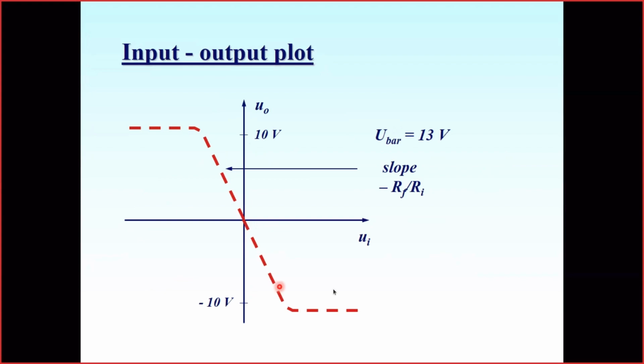So it's not a very high class amplifier, and that's why the maximal voltage it can produce is about 2 volts lower than the power supply. They are not perfect rail-to-rail amplifiers. They provide a maximal output voltage about 2 volts less.